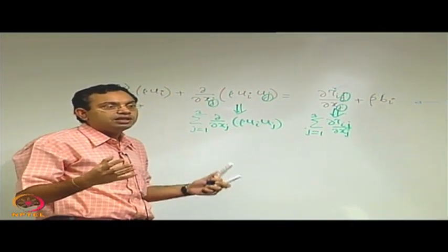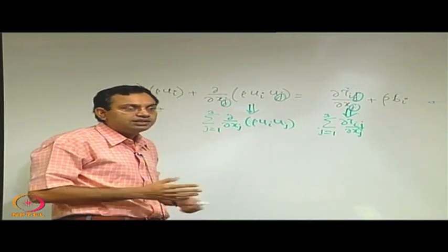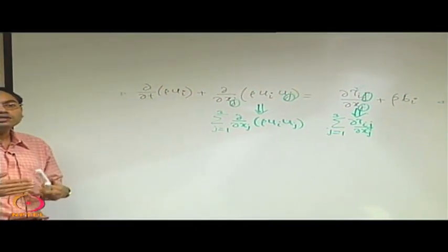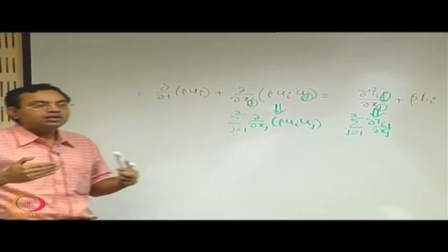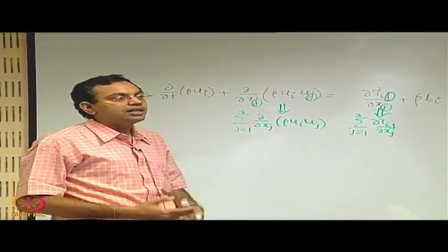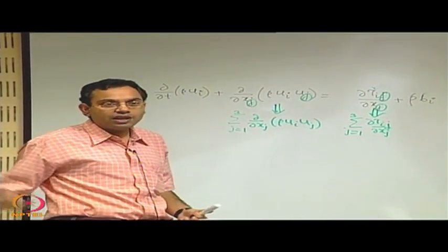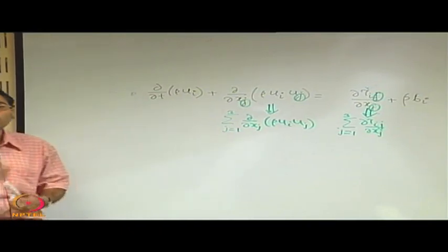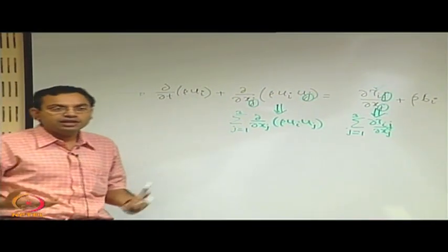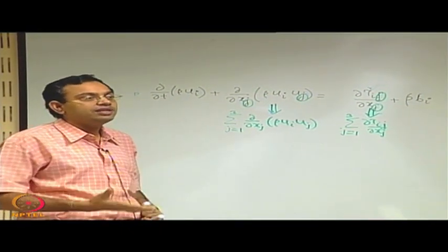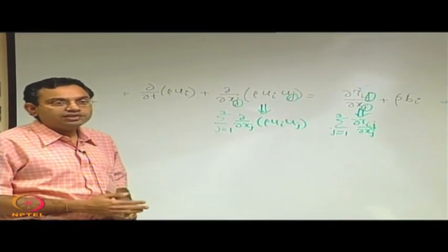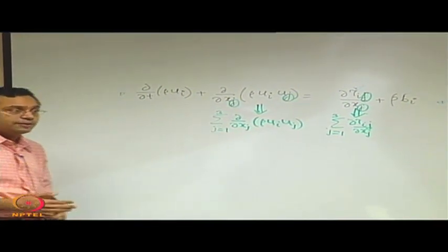Linear deformation may give rise to a volumetric change. So, all these are expressed in terms of rates for fluids, because the understanding is fluids are anyway continuously deforming. If we allow more and more time, deformation will be more and more, that is not a quantification of anything. Quantification is the rate at which that deformation is taking place, or the rate of strain, so to say.